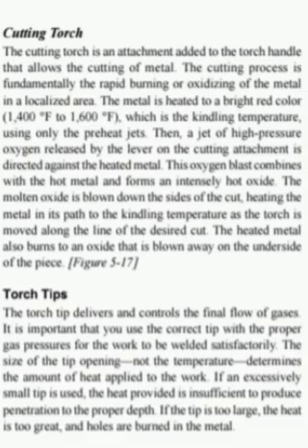Torch tips. The torch tip delivers and controls the final flow of gases. It is important that you use the correct tip with the proper gas pressures for the work to be welded satisfactorily. The size of the tip opening, not the temperature, determines the amount of heat applied to the work.